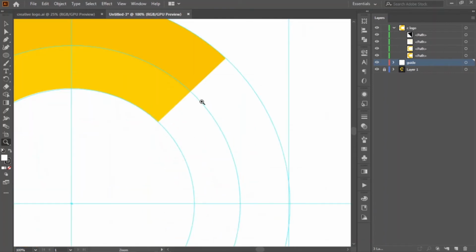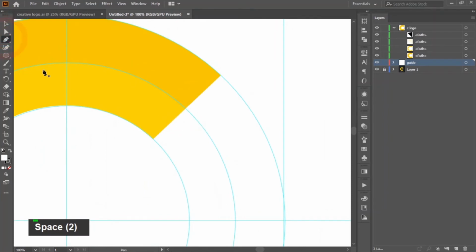So how can we do that? We're going to use this pen tool again. Point to this point, and then to this point, but do not let the mouse go. I mean, just keep holding the left mouse button while you drag this, while you adjust it.